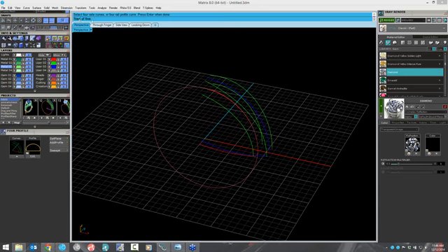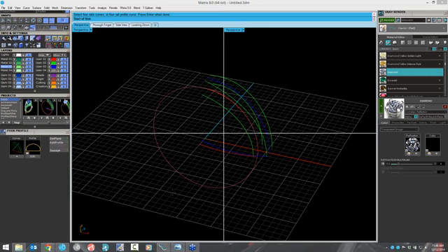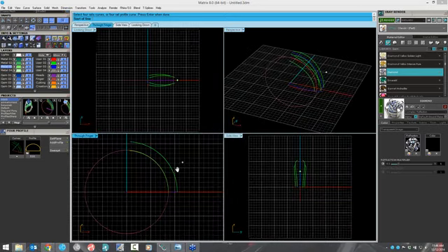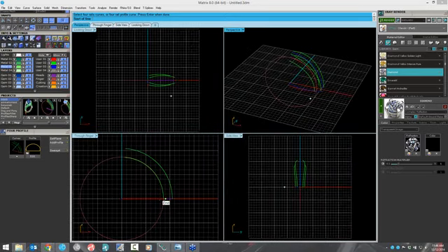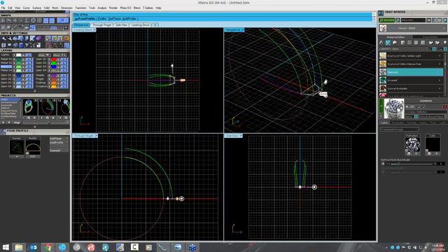You can see it says start of line. Here's my profile. I'm going to turn on project and head over to the through finger viewport, and place a profile through these 4 curves, like so.